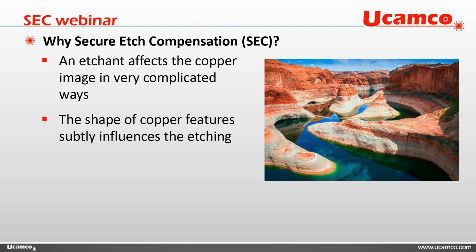And actually, this is also what happens if you're etching. If you have the etchant, it will run between your tracks. It is predictable, but it's more complicated than you think. Because you are etching away a little bit of your copper, you have to compensate. You etch away a lot of copper, obviously, but also from the width of your tracks. So that would be the walls.